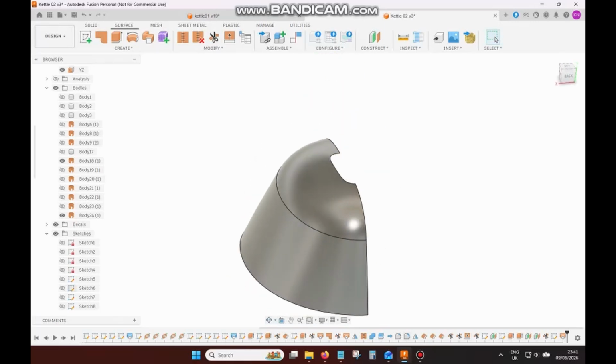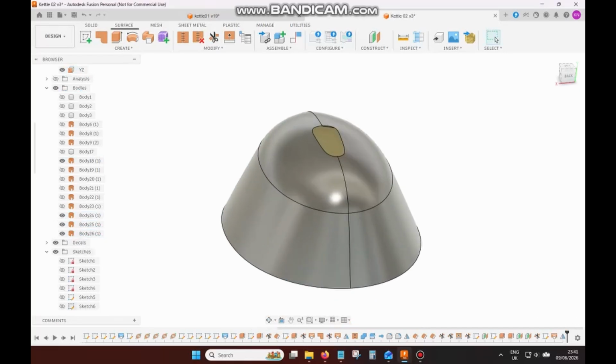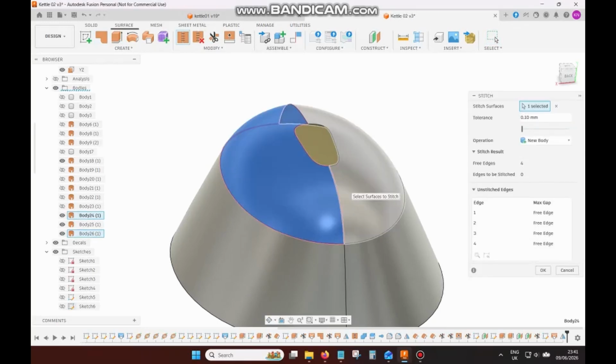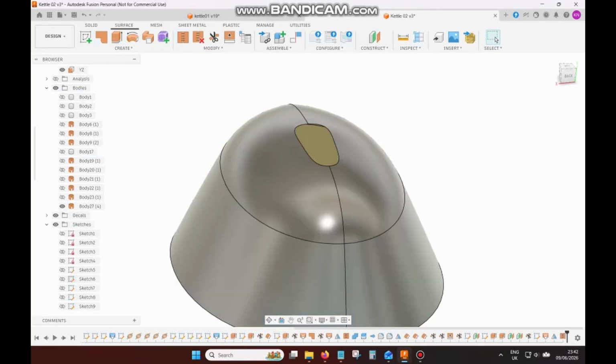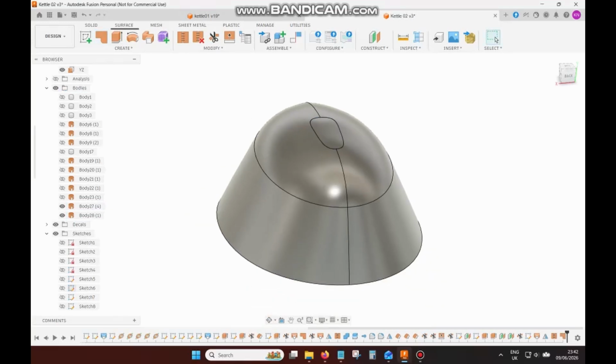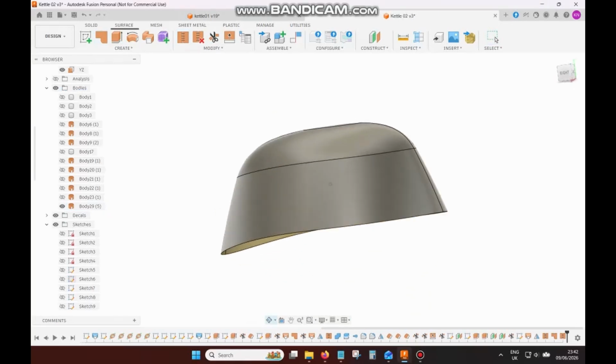So now we've got a fairly nice shape for the stopper with a kind of hole in the top. What I'm going to do, I'm going to mirror these over. Mirror faces, use center plane. And then I'm going to fill that patch in the middle. Oh, sorry, I'm going to knit these things together. And then I'm left with that patch in the middle, and I'm going to make sure that is not just connected but curvature continuous if possible, and that'll be as flowing as possible.